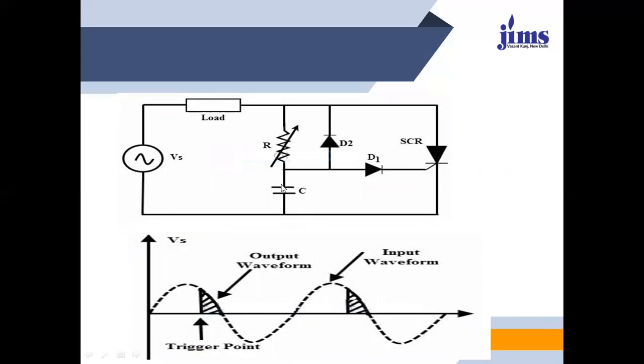But whenever the RC circuit is implemented over here, at that moment the variable resistance will offer a high resistance, so the charging of the capacitor will depend upon it until we get a specific value of voltage appearing across the gate side, and then the current will flow through it. Otherwise, the capacitor will be charged with the help of this, and the charging period will be defined on the basis of the resistance.